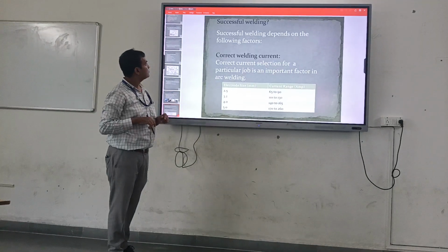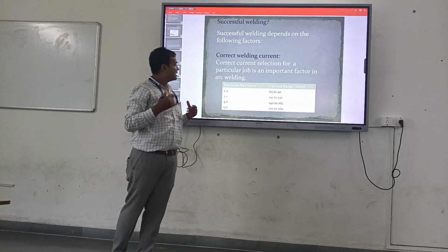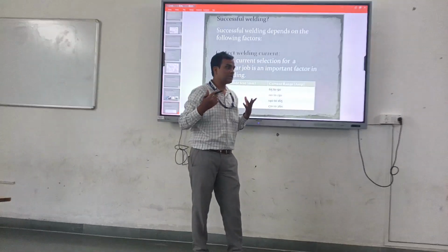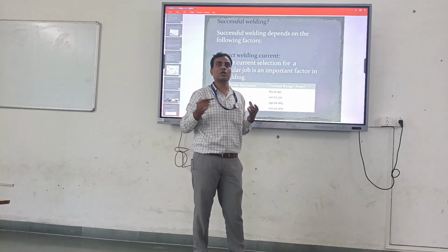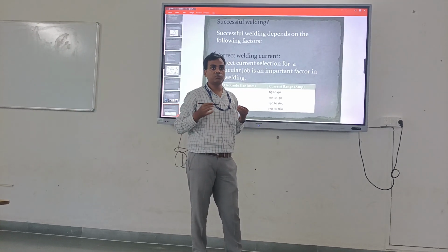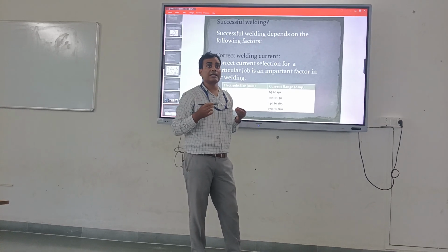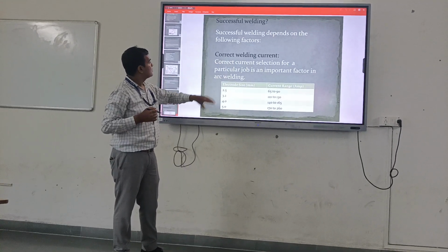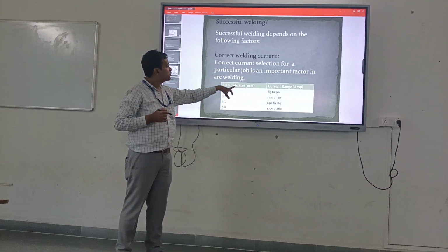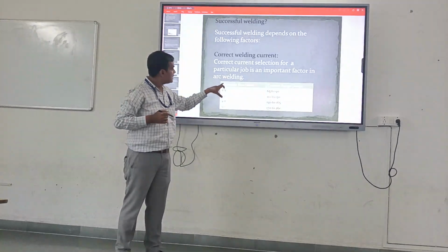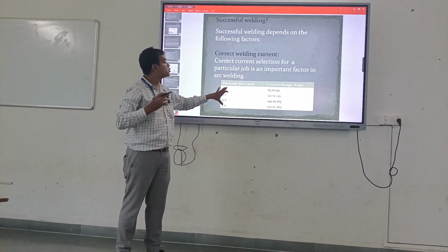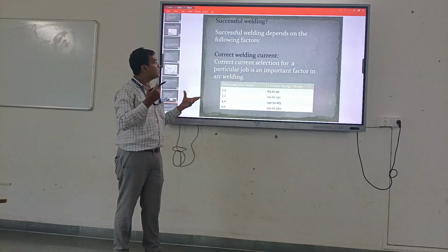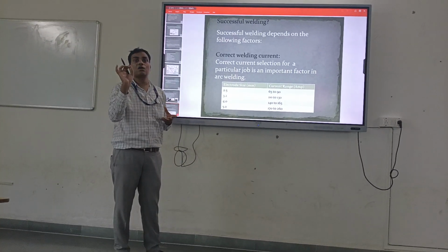Next one is how I will know whether the welding is successful or not. Whatever I did during the welding process, or whatever part I joined by electric arc welding, whether that is successful or not, I have to go through these things. For correct welding, I have to know how electrode size and current range are defined. So we have to consider the thickness of the workpiece.